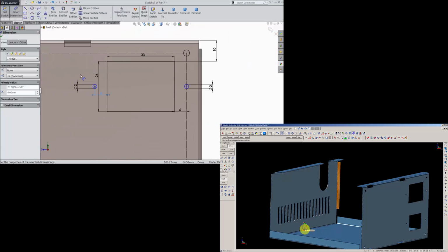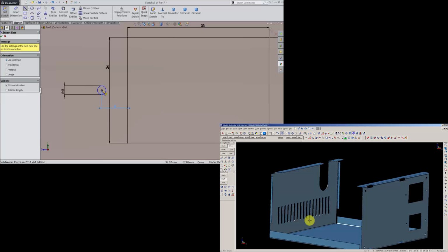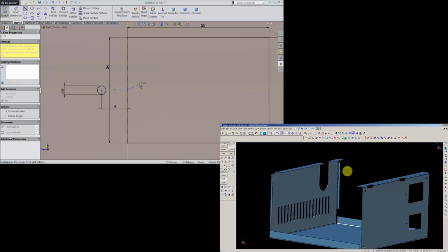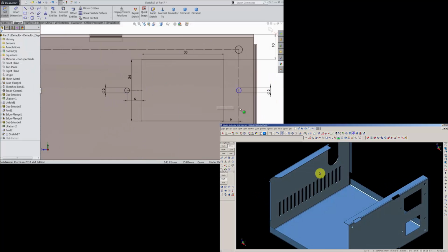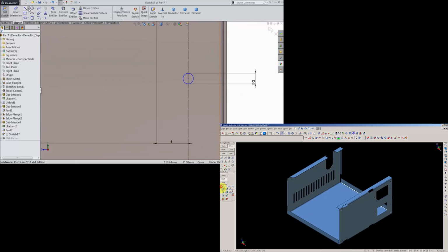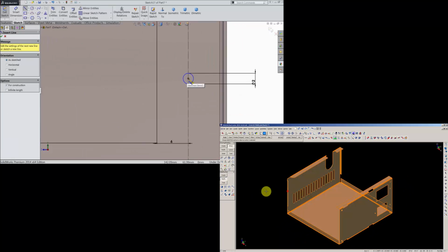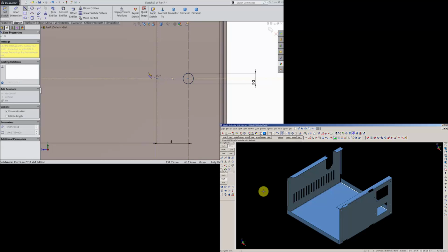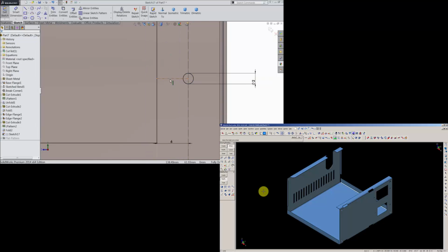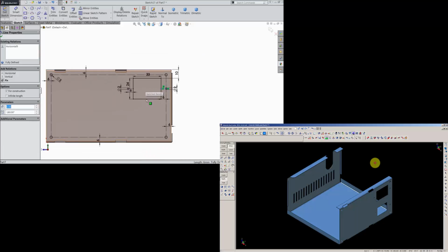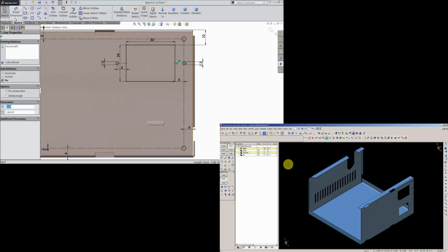This also 6 mm. Select this midpoint. Here also just connect one midpoint, so this geometry will be defined. Make sure it is horizontal. Now we will make one more cutout in bottom line.